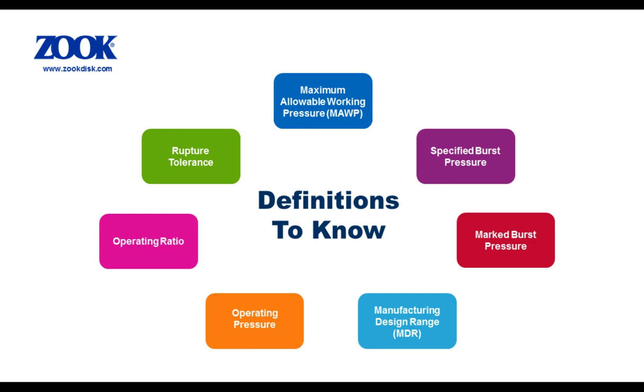Common criteria include the following: vessel maximum allowable working pressure, or MAWP, specified burst pressure and temperature, marked burst pressure, manufacturing design range, normal system operating pressure, operating ratio, and rupture tolerance.